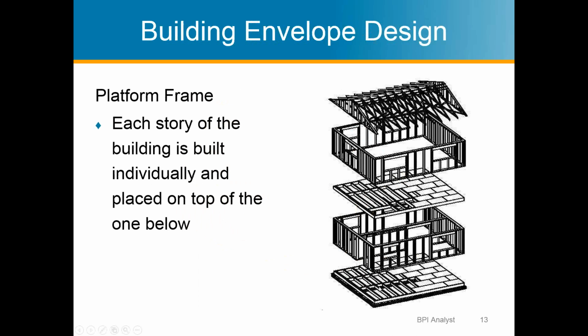Okay, so what we see with balloon framing is, this stud here that's a little shy of 8 feet tall now could be, well, it's going to be more than 16 feet. That's assuming an 8-foot ceiling, right? So this stud is going to start at the bottom of this plate, go through the subfloor, through the wall, through the next floor, and through the next wall, and then this one stud is going to terminate in the attic area.